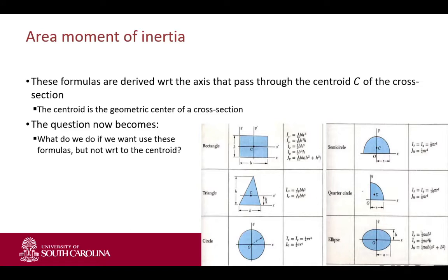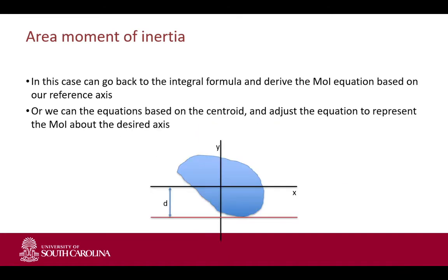What we basically do is say, okay, we want our moment of inertia on a different axis system than the centroidal. So we use what's called the Steiner theorem, which says that if you take the moment of inertia on the centroidal axis and reposition it to a different axis, the moment of inertia is equal to the moment of inertia of your centroidal axis system, Ixxc, plus the area of your cross section multiplied by the distance to your new reference system squared. So if this is your centroid and you have your moment of inertia defined around your centroid, that would mean that Ixx is equal to Ixxc around the centroid plus the area of the cross section multiplied by d squared.